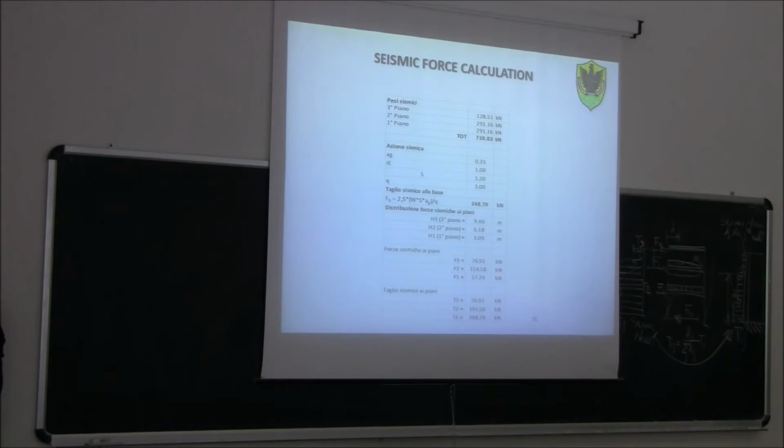When we talk about the mass, the seismic weight, like we said yesterday, the seismic weight is basically the mass of the floor plus what is above the floor, so plus the mass of the content. When it comes to the wall, I'm talking about partitions, we assume that half of the wall above the floor and half of the wall below the floor are considered when I calculate the mass of a generic floor. In fact, on the roof, we have only half of the wall, the half below the roof. On the foundation, the half of the wall insists directly on the foundation, so it is not considered as seismic weight.